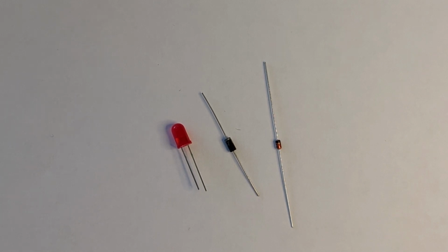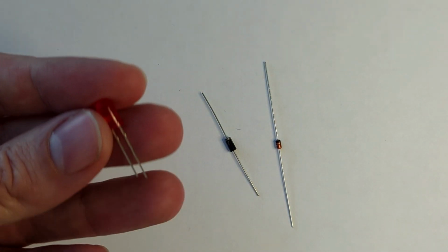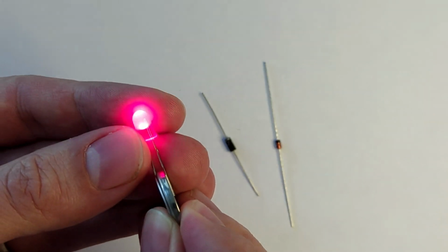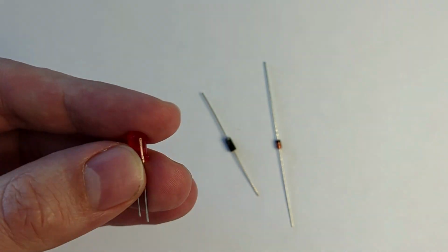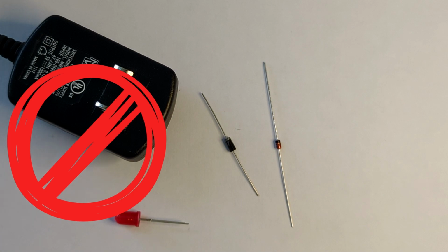In some cases, something else in your circuit provides a current limit. And if that's below the limits of your diode, you may get away without a resistor. A fun example is these coin cell batteries, which can't deliver a lot of current. I can connect them to an LED with no resistor and nothing will blow up. Don't do this with a power supply or a bigger battery.